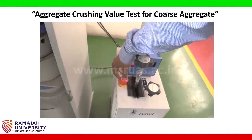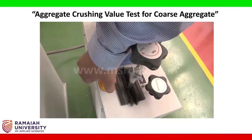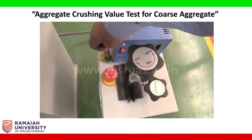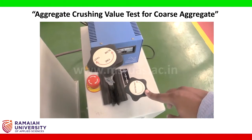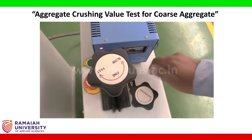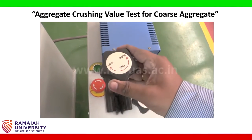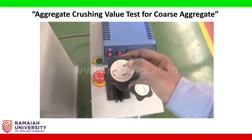Initially the emergency button will be in the on condition. I need to make sure that it is off. If you rotate it, it will come up and you can operate the machine. This is the start button. We need to press the start button, and there are two levers present. One is the load release lever and the other one is the load lock lever. And there is one more lever which tells you about the rate of loading from slow to fast.